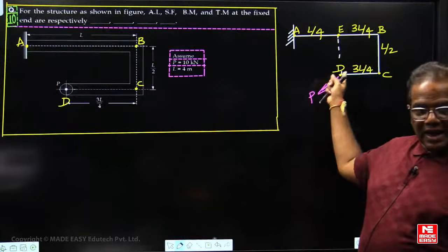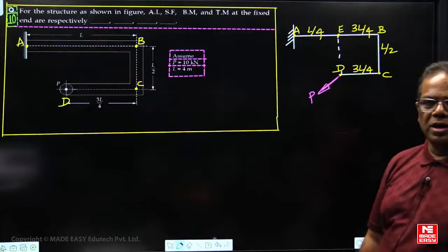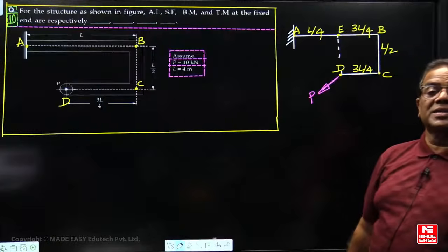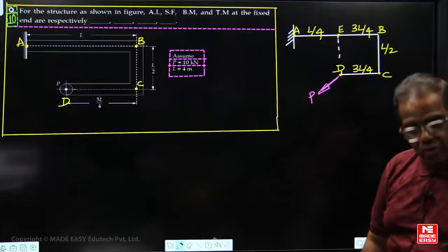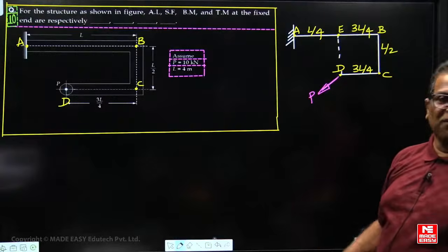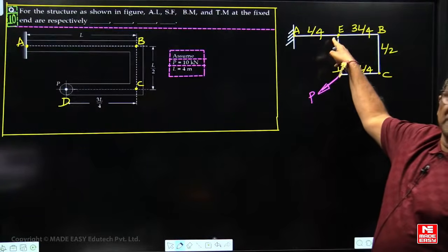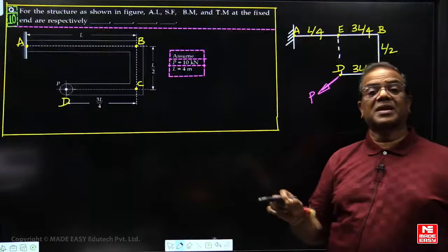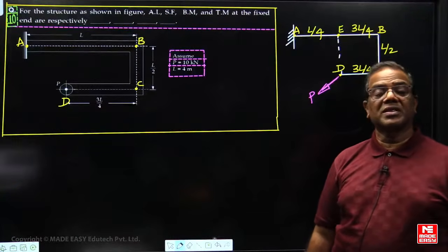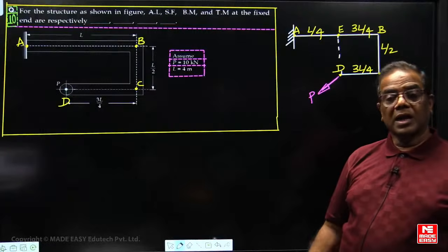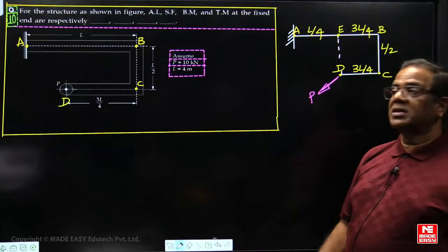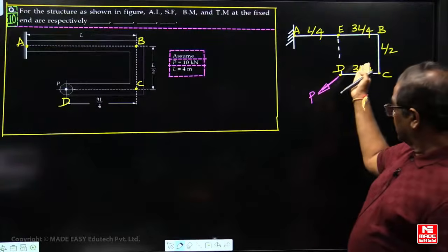This is an inclined line, perpendicular to the plane of the board. I was asking at A. So for this member, this will become a horizontal eccentric transverse shear load. What should be the first step now? Introduce two dummy forces at E. Whenever there is an eccentric load, what is the concept? Two dummy loads should be introduced such that they are parallel, equal and opposite, and parallel to P. So this is the outward.